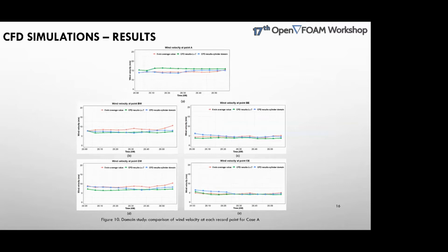So finally we come to some results. The k-omega SST model and simpleFoam are applied for my study. In order to create an equivalent environment with field monitoring, every numerical time step is deemed as a second, and the average value of every 60 time steps is regarded as conceptually equal to the 1 minute average field data, and so on. So finally, we can compare the 5 minute average field data with the CFD model results.